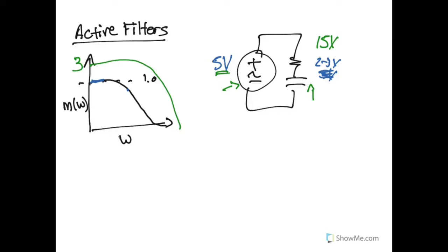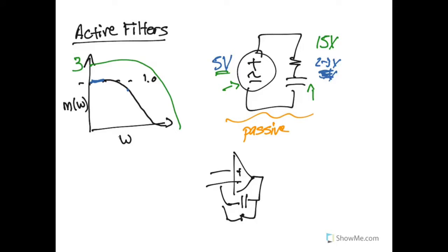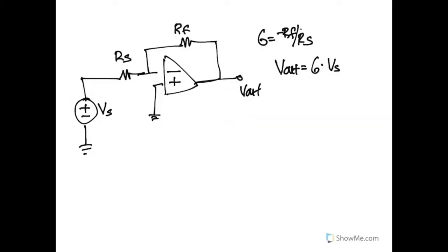And so in this series of lectures, we're going to distinguish between filter circuits that have just passive components, these RC components, which we're going to call passive filters, versus new types of filters that will actually have op amp components in them, and these op amps will allow us to amplify our signal even after it's been filtered.